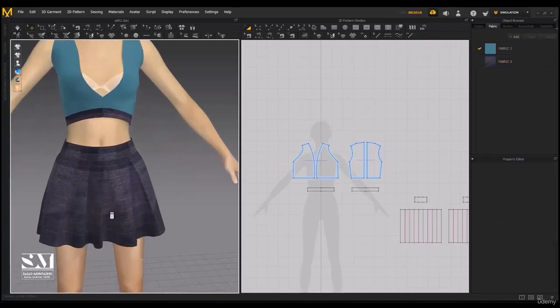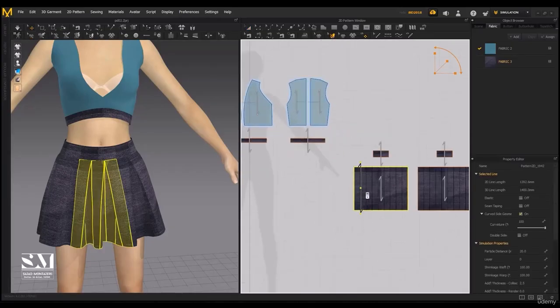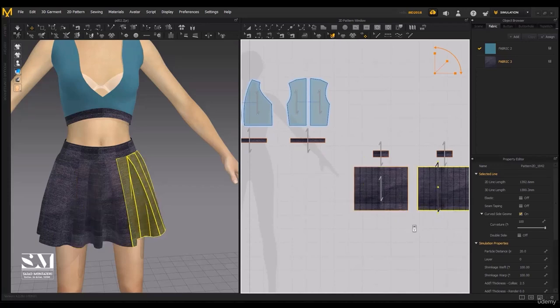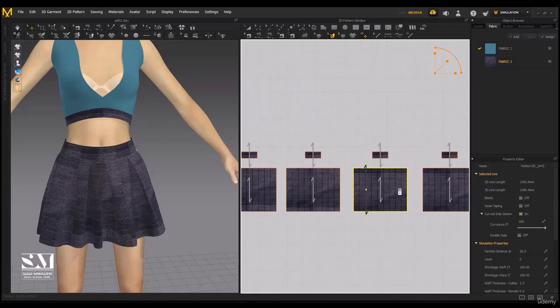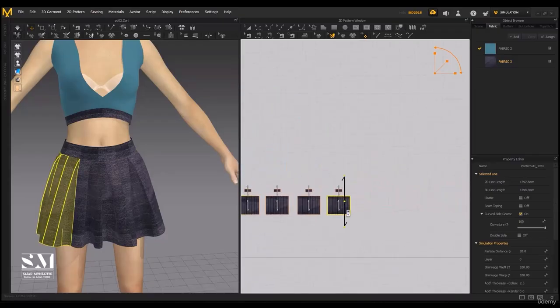If you want to change the fabric texture because it looks too repetitive, we've already learned the edit texture tool. For example, I can select this skirt section and shift the texture slightly upward or downward. Spend a little time adjusting only the parts that show up in the render. You don't need to fix every section. By doing this, the repeated pattern disappears and no longer looks like the default tile.